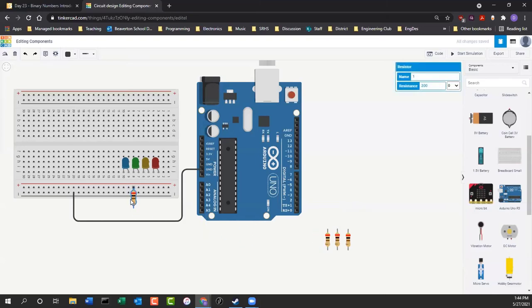So what I'm going to do is off of the short leg, oops, I didn't do my spacing right. I'm going to scooch these up just 1 slot because I need to put my resistors there. And I'm going to connect them. I guess I have to scoot them up too because these resistors are a little bit taller. So again, it doesn't matter where in the row I connect the LED, but now I can connect this directly to the negative power rail.